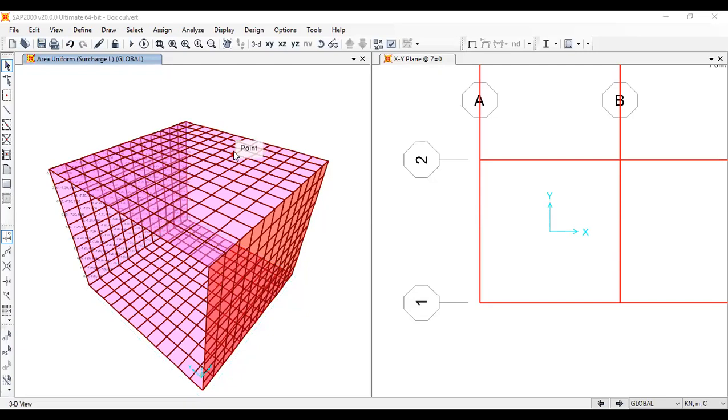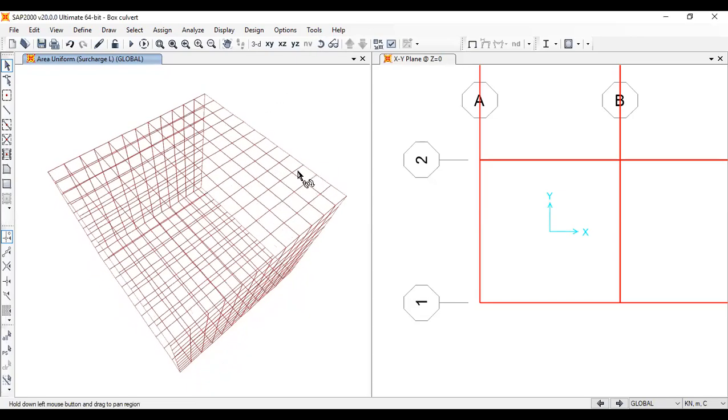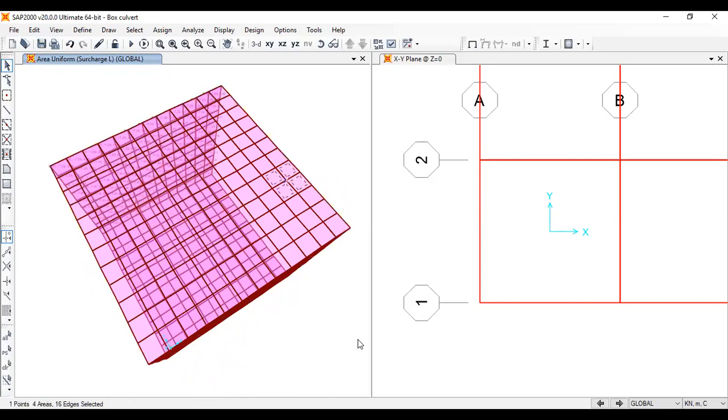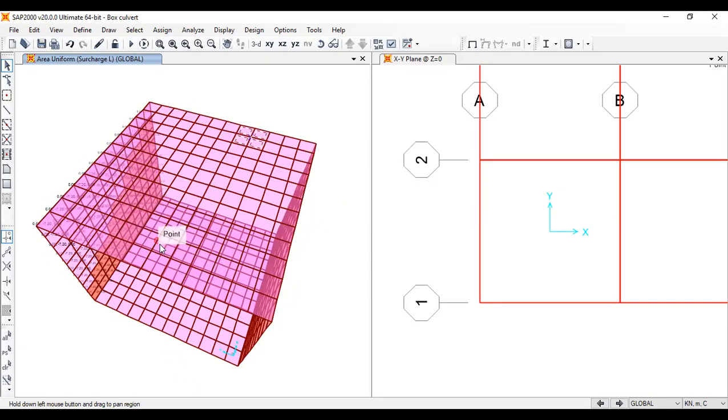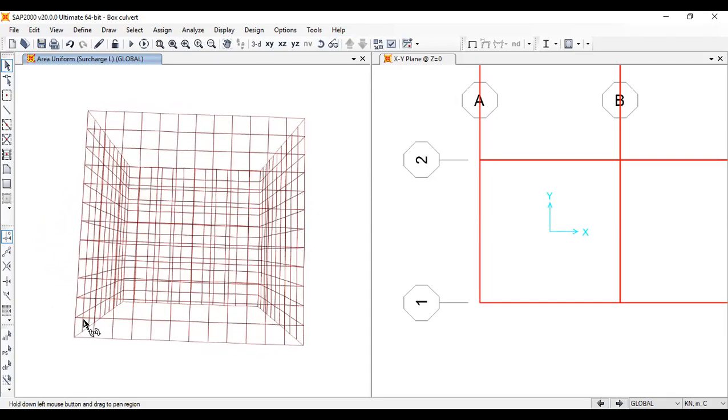So the next thing is you need to apply the HB loading due to the vehicles. So the critical location is when two wheels, this is the y direction, like y direction is the road direction, right? Perpendicular to that you will have the axles, right? So the critical loading is that you will have two wheels just past the center line, and the spacing between the axles is 1.8 meters, right? So the dispersion, meaning the load distributed area, is about 1 meter, let's assume. You can always calculate these things according to any code. Don't worry.